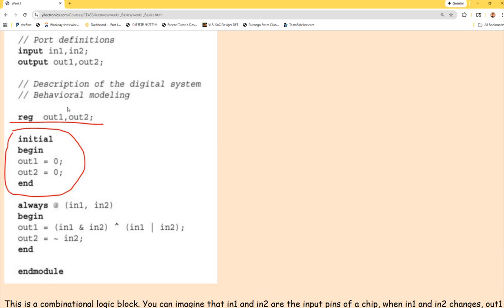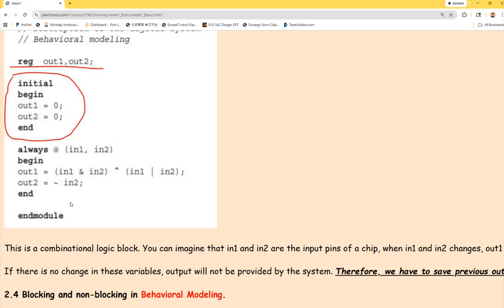These are just for simulations, not really for hardware. And also there are very tiny differences between synthesizable and non-synthesizable always blocks, and very little differences in the syntax. So whenever the tool reports errors and you notice it, just make notes on that. So you know that, hey, this is not synthesizable. In the future, we just don't use it. So that's the concept over here.